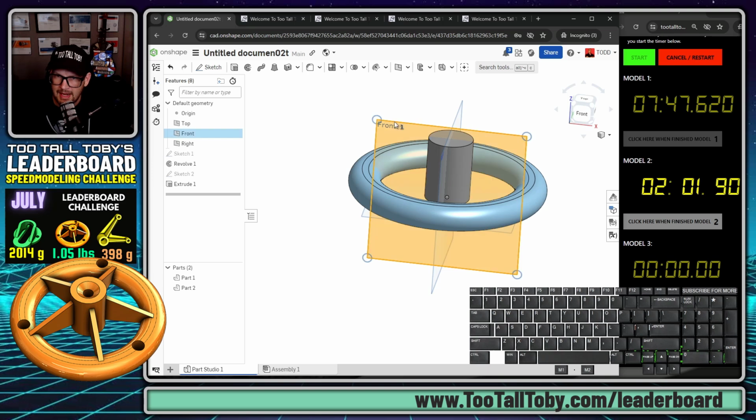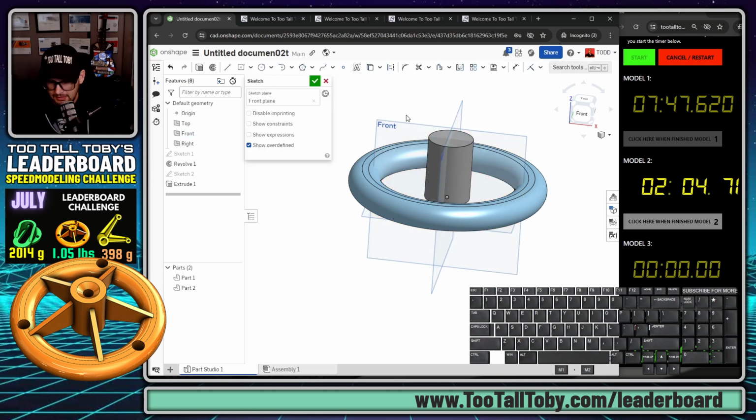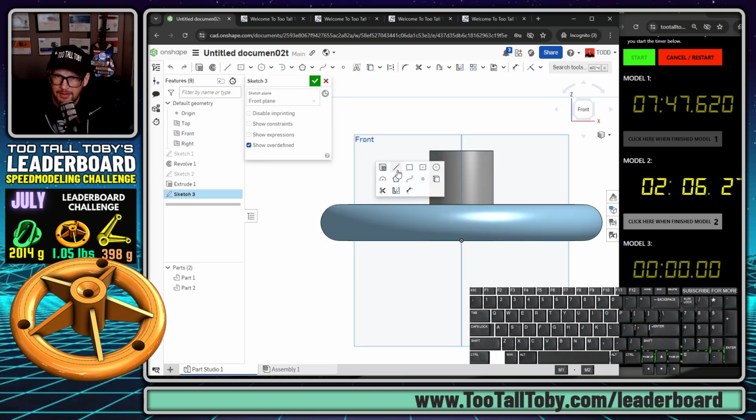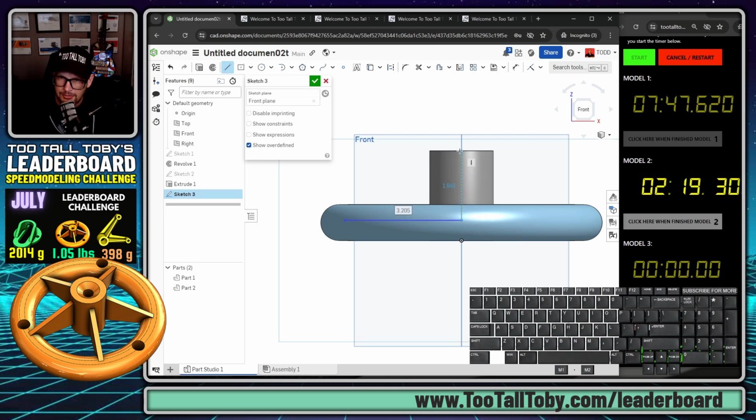And now we're ready to create that kind of rib shape. So front plane, begin to sketch, orient our view. And for that rib shape, you'll notice that the dimension is being called out as collinear and midpoint right to this location here, right to the very top. So you can make sure that as you're creating your geometry, you're coming over here right to the origin, coming up kind of to this location. We can add the relationship in just a moment.